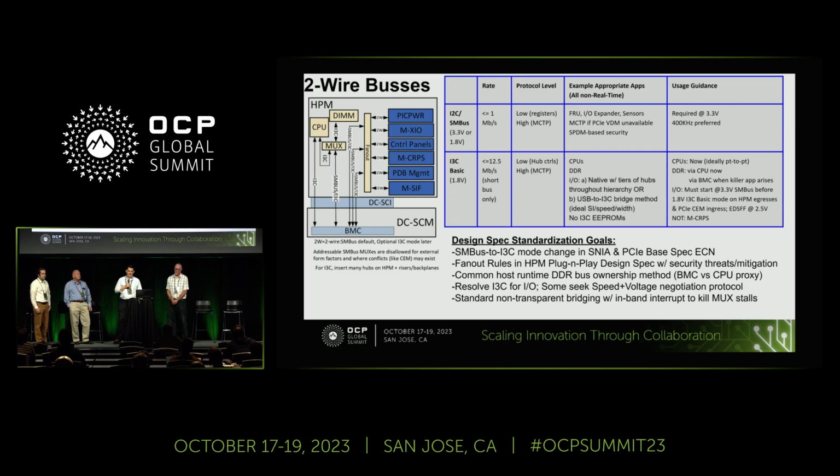From an I/O perspective, there are some issues with the long buses and turnaround times and things like that. We think one of the enablers, especially with things like the DC-SCI, where you can't provide everyone point-to-point or with as little fan-out as possible, is tools like the USB-IF USB to I3C bridge specification, which came out a year and a half ago. It's one method where you can use a pay-as-you-go model. Instead of plumbing I3C from your BMC throughout the system, you could say, now I'm using managed USB, so I have ideal bandwidth and signal integrity right at the destination I need to go to, such as on a backplane when I need to fan out to a bunch of NVMe drives, for example.